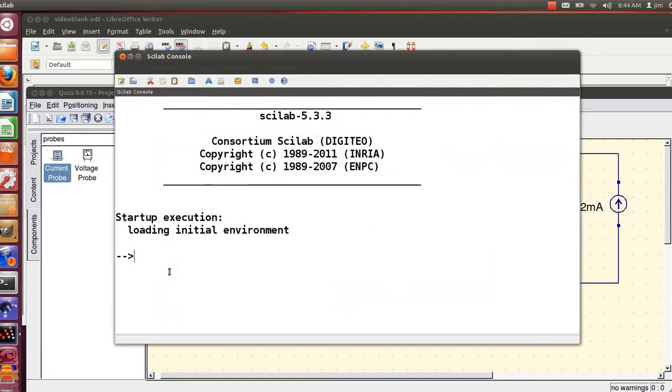I'm going to call up my Scilab here, and I'm going to say, okay, Problem Norton equals, and I'm going to do the matrix thing. So my first equation boils down to 0, 0, 1, 1, and 0.02, because I've got to convert it to milliamps. So I want to get rid of the units. So that's my first line.